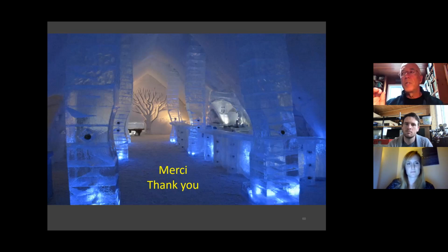But essentially, what you see is that starting at 20% water content, so that's gravimetric water content, you start having some settlement. But between 20 and 30, it's really modest settlement. Between 30 and 40, it begins to be more significant, and not sure exactly we should draw the line at 40 or 50, and anything above that 40 or 50 would be high ice content, based on gravimetric water content measured on the sample, as long as you're recuperating a full undisturbed sample and you're melting the sample and testing the moisture content. So yeah, that would be my range, but other people might have different values than me.